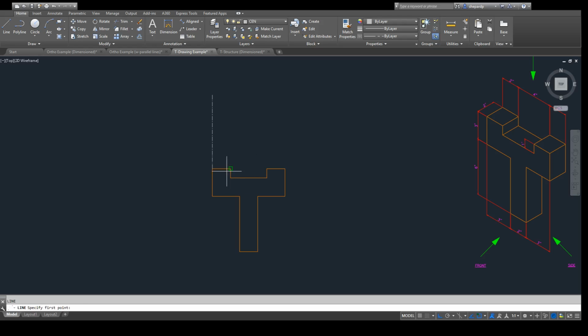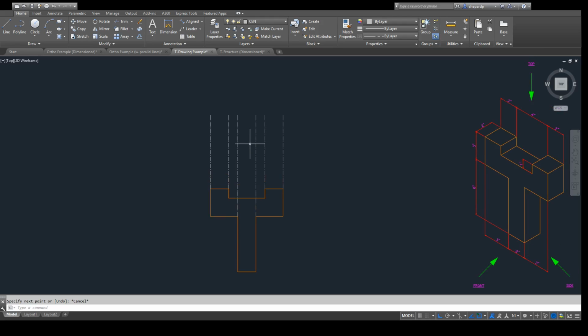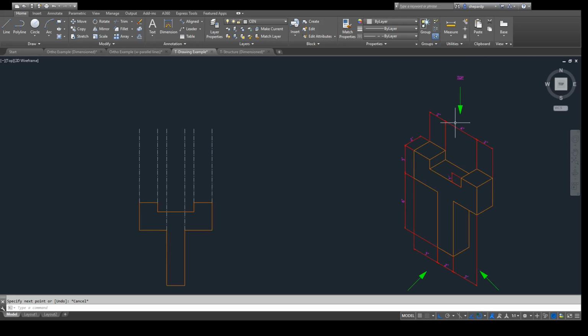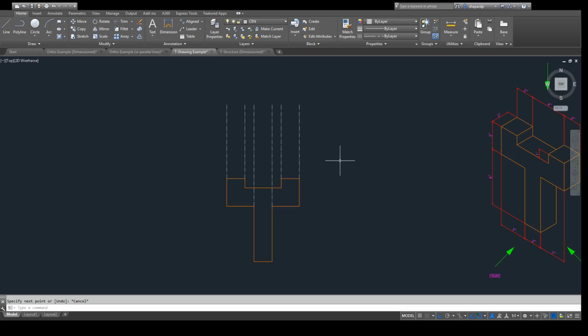From the top edge. Alright, another 8 inches. We'll do that for each of these edges. And there are 2 more edges we shouldn't forget right here. They are the bottom. They're essentially the lines that would be going along this bottom right here. They're an edge. Now, I won't be able to see them from the top view, but we will designate them using hidden lines, which I'll show you. So again, the top view, you're pretending as though you're looking down at the given shape from above.